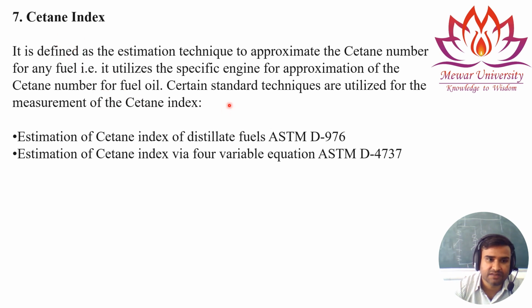We have certain standards and methods to measure the cetane number using the cetane index. The first one is ASTM D976, and the second one is ASTM D4737. This is called the cetane index via four variable equation.